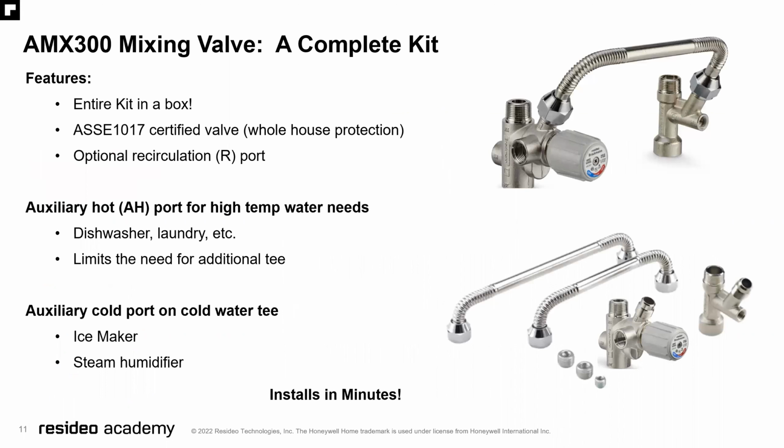The AMX 300 mixing valve, a complete kit. This is what I have in my house. Entire kit in one box. ASSE 1017 certified valve with whole house protection with an optional recirculation port. It also has an auxiliary port for high temp water, so you can go ahead and send hot water to a dishwasher or laundry or anywhere else permitted by code.